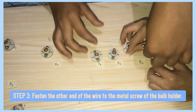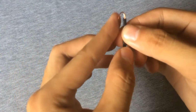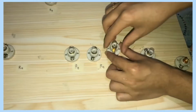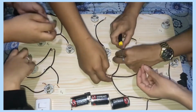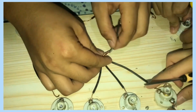Step 3. Fasten the other end of the wire to the metal screw of the bulb holder. Take the exposed metal end of each wire and bend it to the U shape. Loosen each screw on the light bulb holder just enough to slip the U shape of the wire around the screw. Each wire will be attached to its own screw. Tighten the screw, ensuring that the metal of the wires remains in contact with the screw. And now we do the same procedure to connect it to other receptacles until we make a model connection for the electricity to flow on these wires.